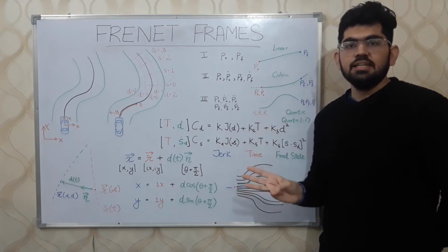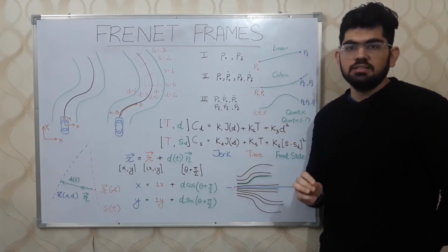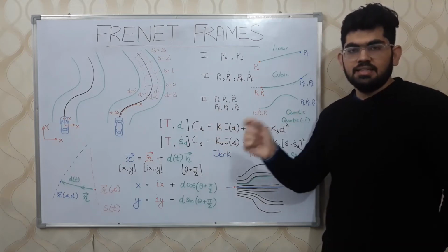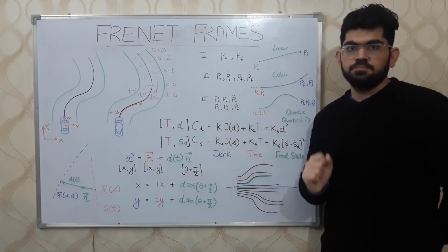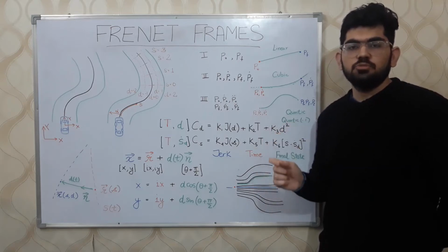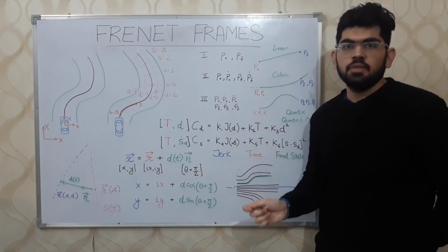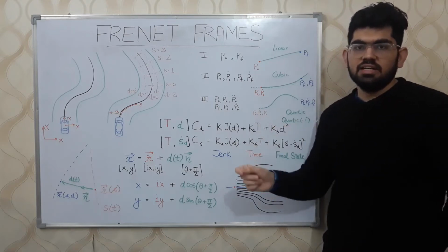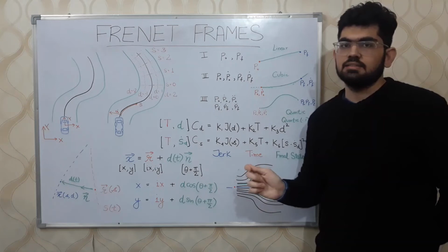For the s-axis, we only have 5 constraints. The initial 3 constraints are already known to us: initial s, the speed s dot, and the acceleration along s. In the final state, we do not have any constraint on what should be the final value of s. However, we have some constraints on the velocity along s and the acceleration along s.